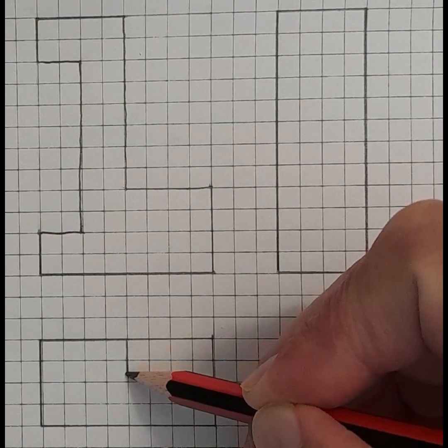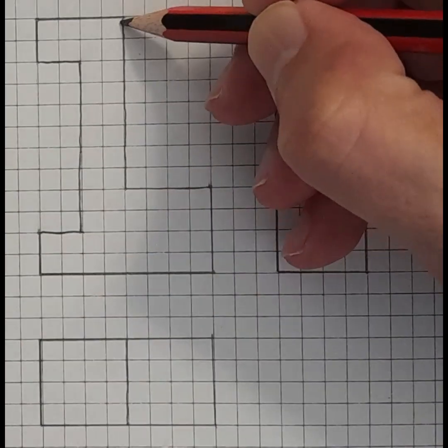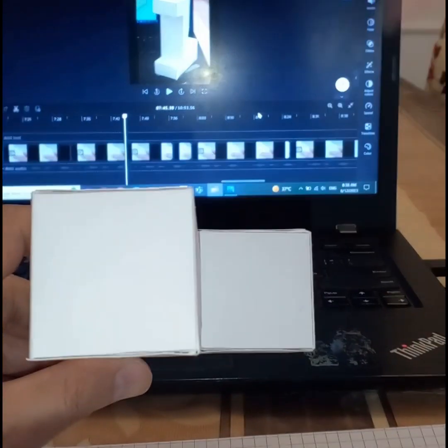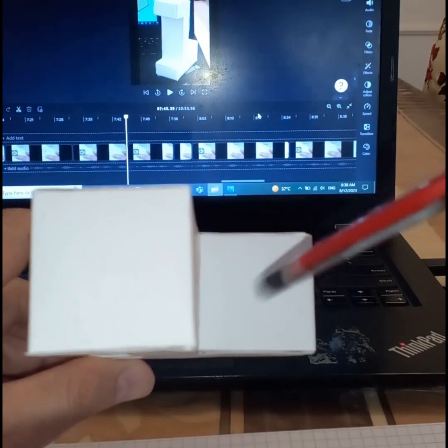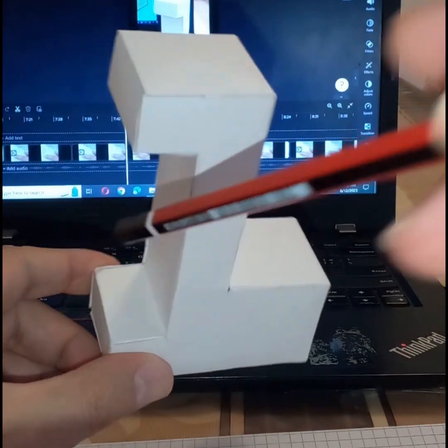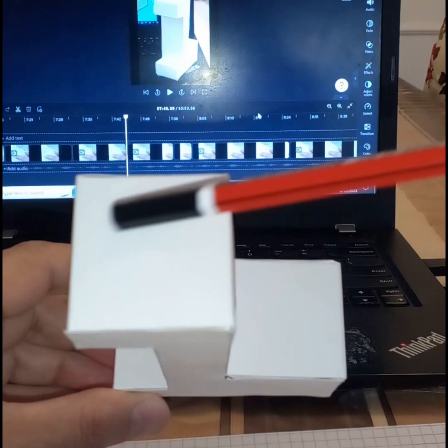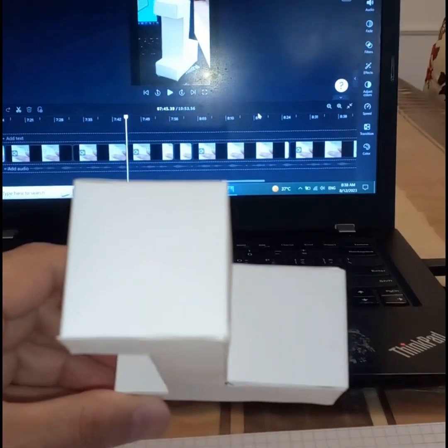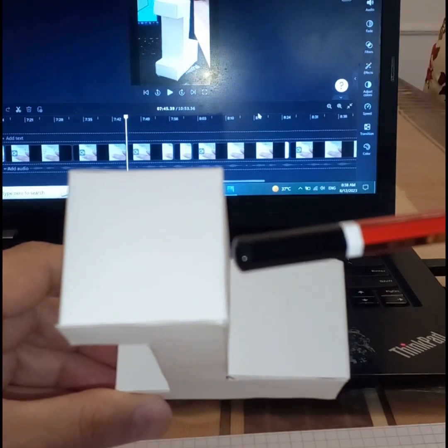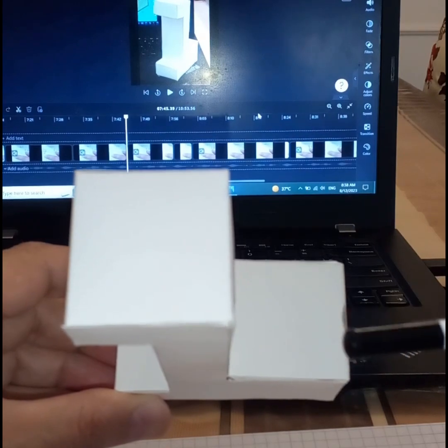like this, drawing the middle vertical line, and of course this vertical line should be aligned with this one. In the top view, we look at the part from this direction, so we draw these two squares. But what about this surface? This surface is hidden by this surface. We cannot see it, but it exists. So we have to represent it in the top view by a dashed line.